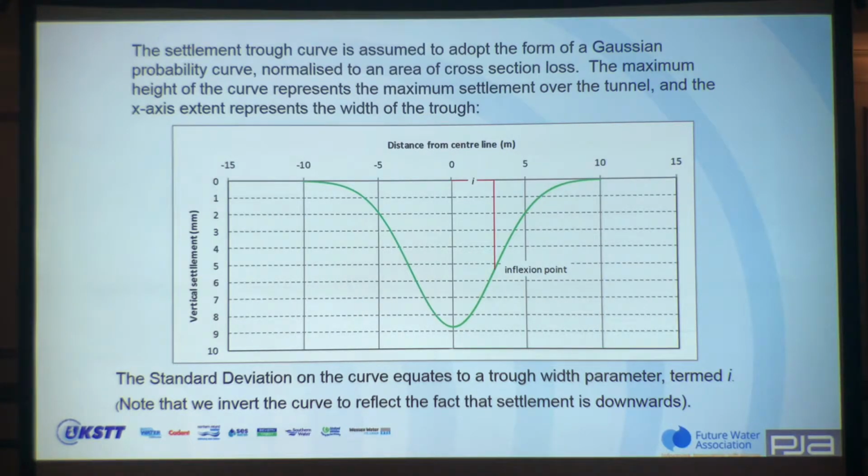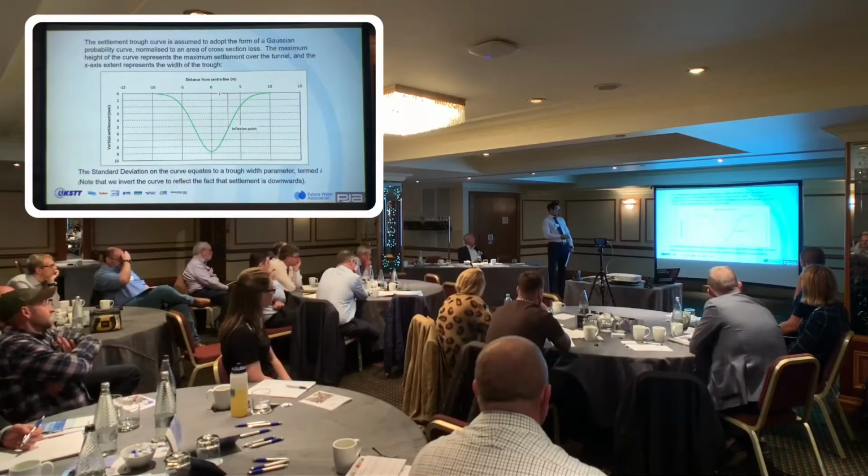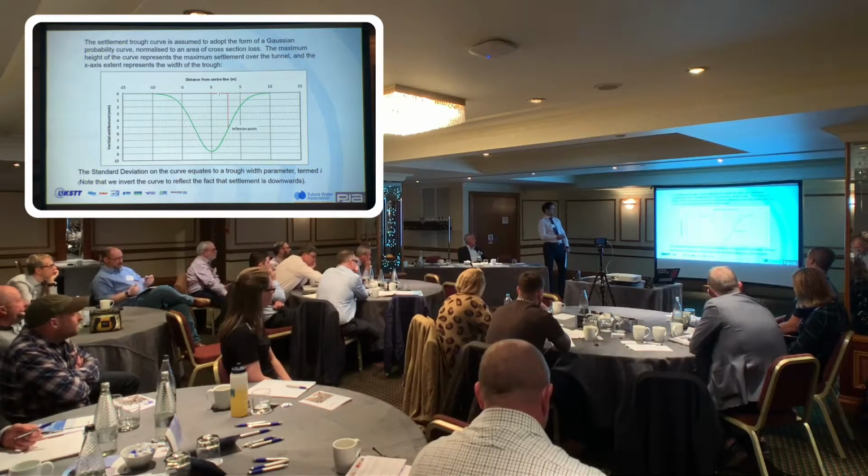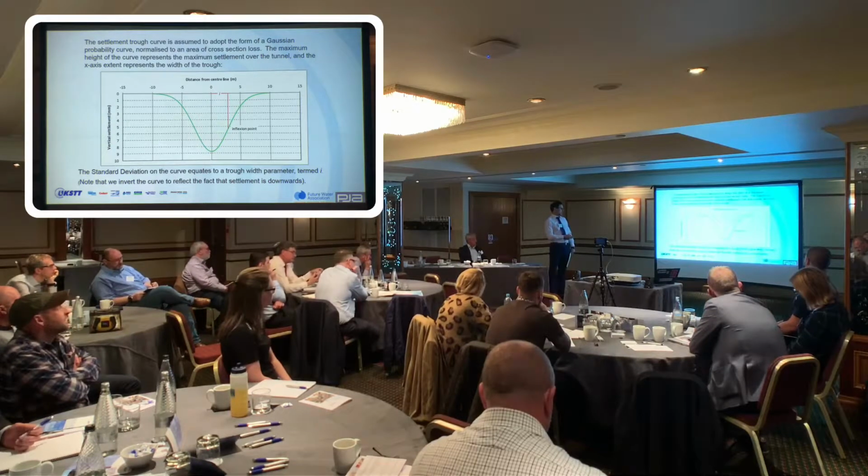This is a presentation of the results of the assessment of the maximum settlement we'll get. You can see that's 9 millimetres, so generally that's okay. But another thing that other people may not consider is the actual gradient of that curve. If you've got a very sharp dip, you're going to feel that if you drive over a road and there's a sudden 10 mil drop, you might feel a little bump. If that gradient is quite gentle, you may not notice it, and a lot of consideration needs to be given to that as well.